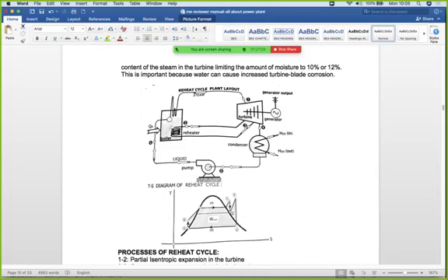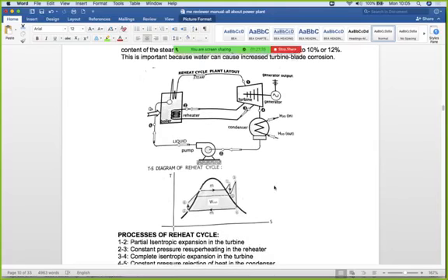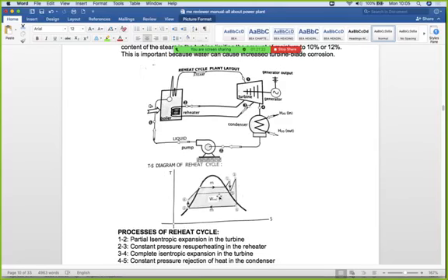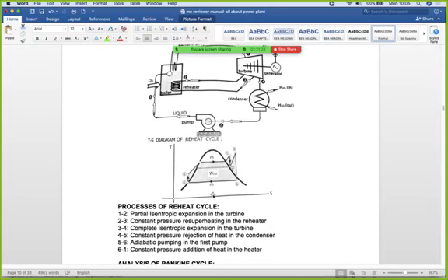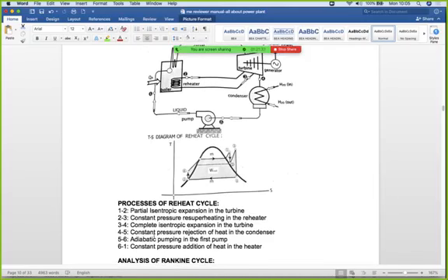The main purpose is to reheat the steam inside this steam generator. So it goes back again to the turbine and releases here. So you have now added the corresponding process, so that instead of 4 processes, you now have 6 processes due to the reheat cycle.